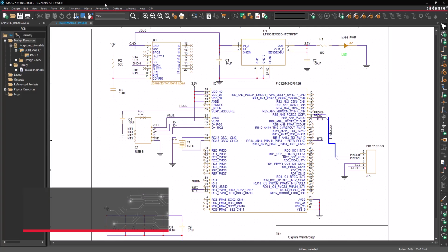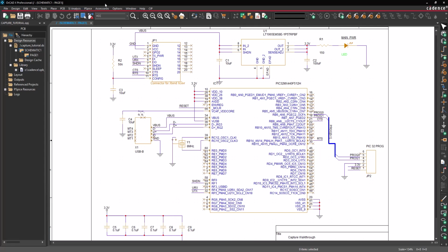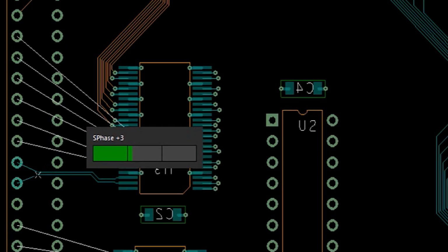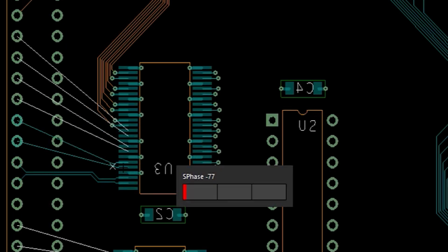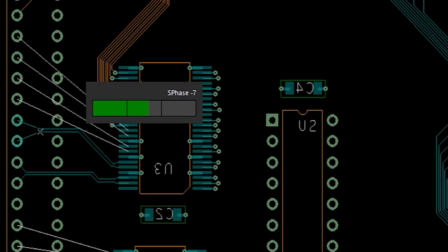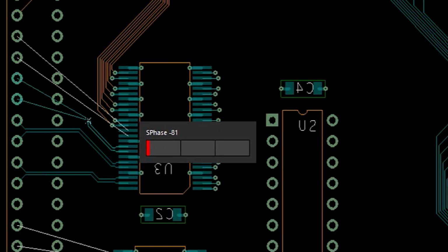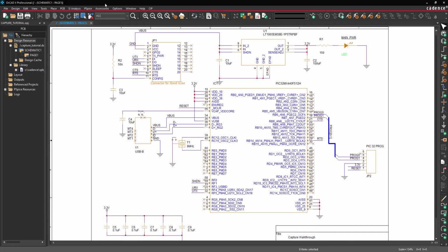In this lesson, we will show you how to define differential pairs manually and automatically. Differential pairs are used for effective noise cancellation and a robust signal path. Differential pair traces are routed together and specific rules can be defined for the PCB layout, including primary gap, neck gap, and more. To define differential pairs in the schematic, select the design file in the project hierarchy.